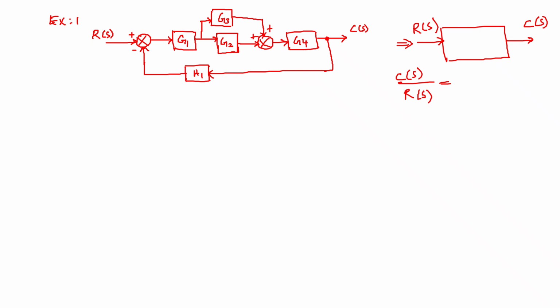We have to eliminate those series and parallel blocks first, then solve for the inner feedback systems, then go for the outer feedback system. If we do not straight away have a series or a parallel block, watch for a takeoff point or a summing point to move ahead of a block or behind a block in such a way that we get a cascade or a parallel system.